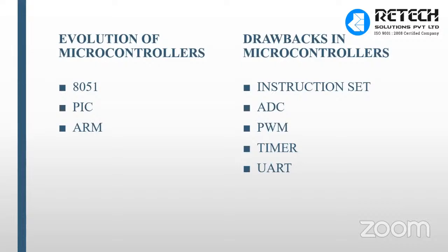In that, port C is used for ADC. In the PIC microcontroller, port C has an inbuilt analog to digital converter. Then pins 14 to 18, these 5 pins, are inbuilt PWM function pins. Instead of the timer IC 555, they used a real-time clock. In PIC microcontroller, and in Arduino also, there is a real-time clock. Using a real-time clock means a timer circuit is not needed.